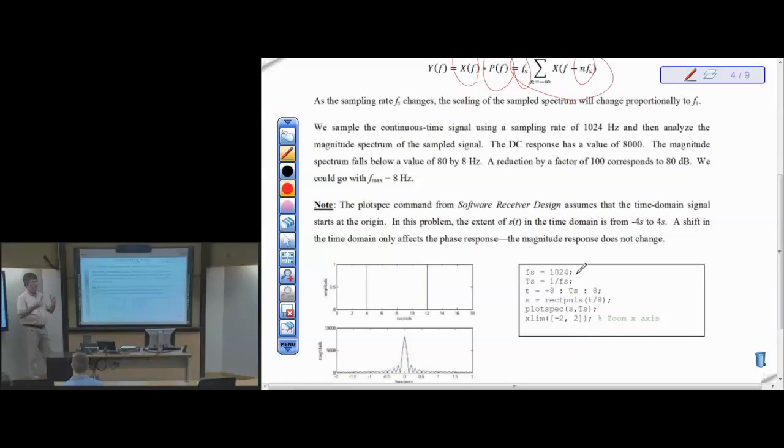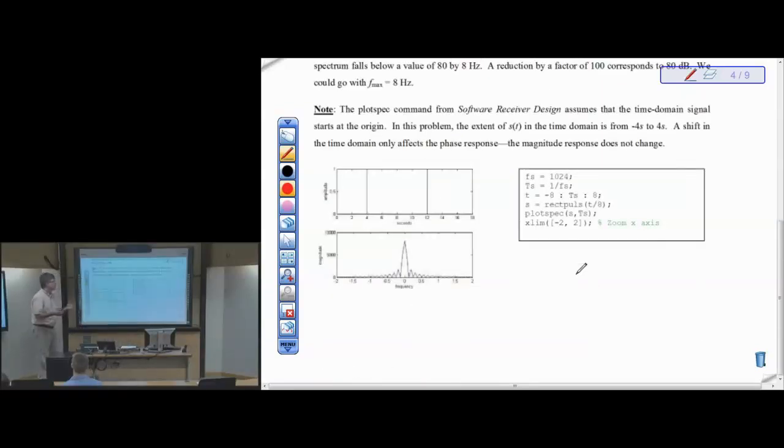And the aliasing will be obvious because the spectral shape suddenly changes. There's something crazy, and you found aliasing that you can see. There's always aliasing, but not always affecting what you see or what you hear. But eventually you get to a point where you see it. It's catastrophic, or it's really dramatic. Okay. And so you can eyeball this, just from looking at different sampling rates, because the key is you want to make sure that you don't have significant aliasing when you're trying to find Fmax. So as long as you know your Fs is high enough, then you can have some confidence in your estimate of Fmax.